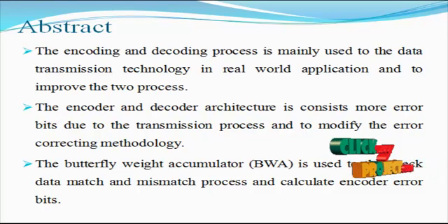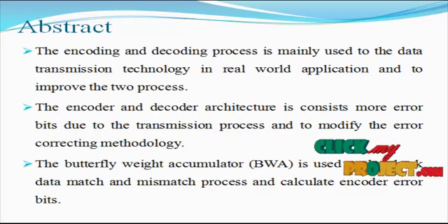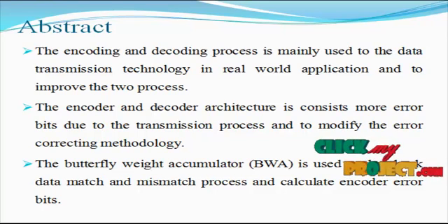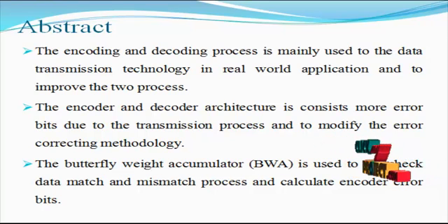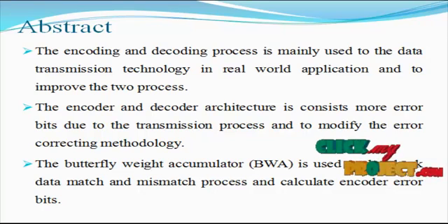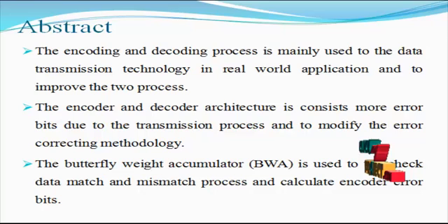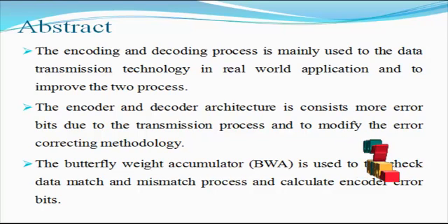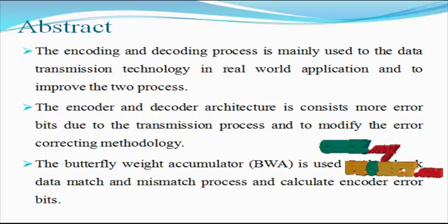Besides, data comparison usually resides in a critical path of components that are devised to increase system performance. Examples are caches and TLBs, whose output determines the flow of succeeding operations in a pipeline. The circuit therefore must be designed to have as low latency as possible, or the components will be disqualified from serving as accelerators and the overall performance of the whole system would be severely degraded.